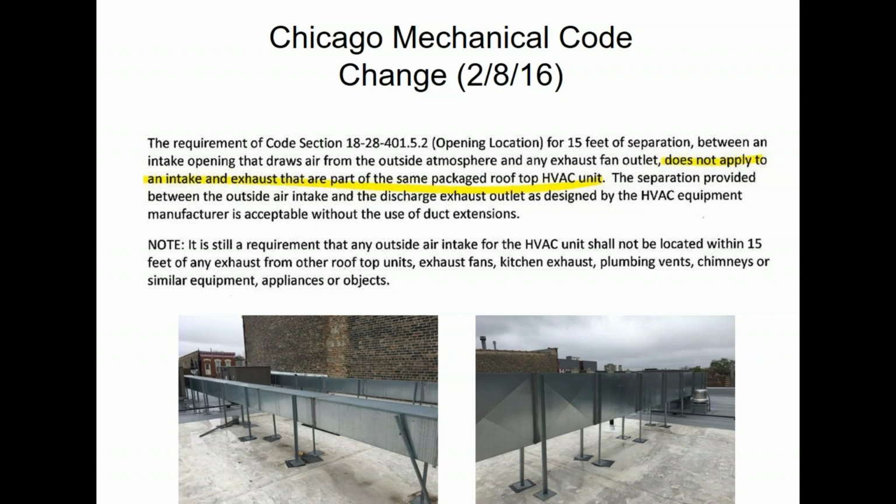A new exception to that: it does not have to be 15 feet away from itself. So it does not have to be 15 feet away from the power exhaust or the barometric or even from the inducer exhaust. They decided that a packaged rooftop unit, someone has designed and engineered it to not have those airflow paths interfere, so you no longer need that 15-foot duct extension. You still got to be 15 feet away from some random bath fan or whatever, or kitchen fan, but not 15 feet away from itself.